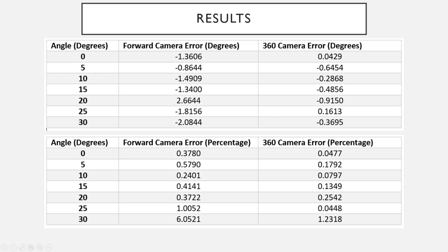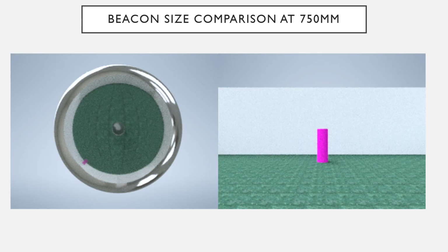In terms of determining the bearing of an object in the field of view, the 360-degree camera system, utilizing the hemispherical mirror, was drastically more accurate relative to the forward-facing camera system. However, what this report does not investigate is the significant loss of both viable range and range calculation accuracy that the 360 camera system suffers from. Due to the curvature of the spherical mirror, objects at an increased distance will shrink in the image faster than the same object viewed by a forward-facing camera system.